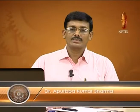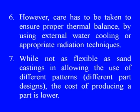The cavity design for these molds does not follow the same rules for shrinkage as in sand casting molds. This is due to the fact that the metal molds heat up and expand during the pour. So, the cavity does not need to be expanded as much as in the sand castings. However, care has to be taken to ensure proper thermal balance by using external water cooling or appropriate radiation techniques.